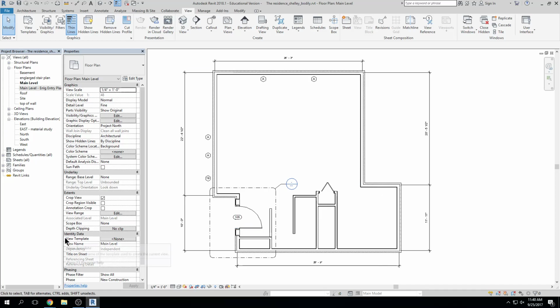There is a way to save that data, right? So if I get my floor plan looking how I want it to look, and the cut line is right, and all the information that needs to be turned off is turned off, and dimensions are turned on, everything looks really good, I can save what's called a view template. If you want to compare it to AutoCAD, it's like a layer states save, right? Where I can click one button and it turns on all of the layer states that I want turned on. It's a way of saving your view settings, essentially, the view template, okay?